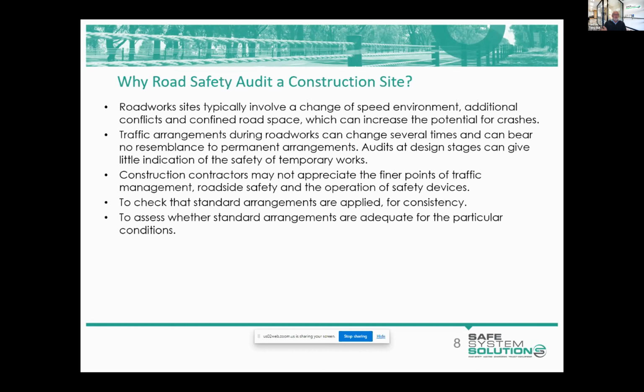Putting it up to 100, probably dangerous, but we have the risk assessment process to give us that information, and leaving it at 40k is bad practice, especially when there's no workers on site. Unless, and I'll put the caveat on it, unless the site conditions demand that. It might be the lanes are so narrow. It might be the bridge works, that there could be a conflict because of the temporary bridge that's been put in place. So there's always exceptions to the rules, but that's what we should be looking for.